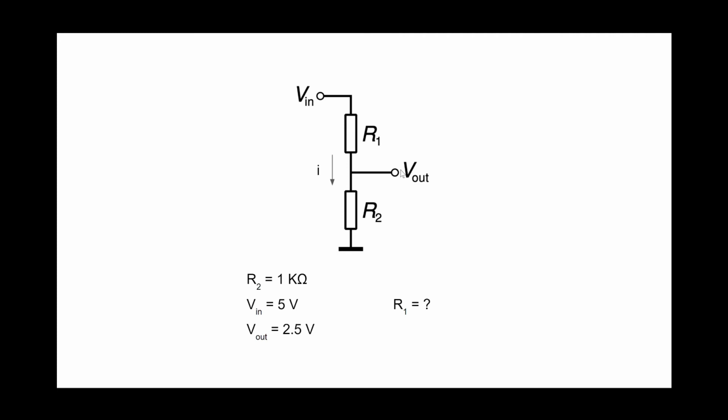If R1 is the sensor we use, that means we can calculate the resistance value of the sensor. If the sensor changes its resistance value depending on the external environment, and if we could measure the resistance change with Arduino, we finally become able to read a sensor.